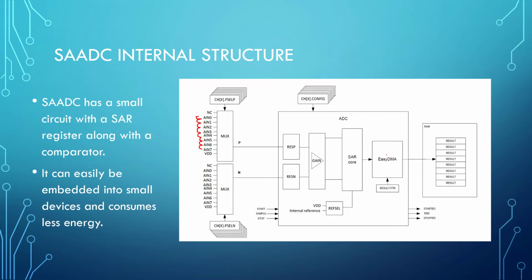Like whether we are doing multiple samples or just taking a single sample. So we can easily use DMA. The DMA basically takes the ADC data and copies it to the memory without the processor's intervention. So the processor can be working on something else, and we can easily read the values. Once the values are stored in the memory, we can create an interrupt, and that interrupt will be called as soon as the DMA transfer process is finished. We will see how we can use the DMA with the ADC in future tutorials.